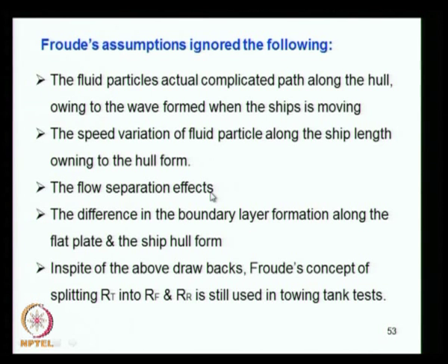Then the boundary layer: the boundary layer formation and flow separation around the plate and around the ship are different, and these flow separation aspects are ignored; only the frictional resistance component is considered.